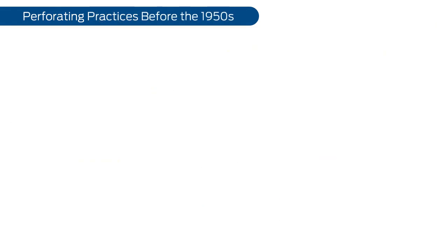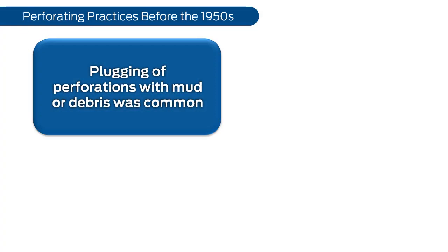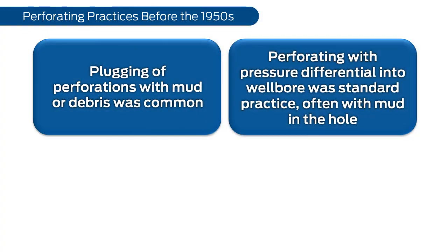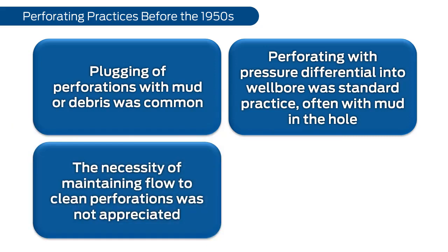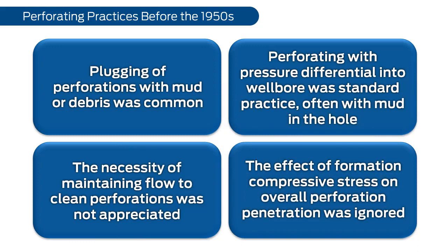Before the 1950s, plugging of perforations was common. Perforating practices and operations were carried out without a concern for wellbore fluid environments, often with differential pressure into the well and with mud in the hole, all of which led to creating perforation damage. The ability and the necessity of maintaining clean perforations was not understood or appreciated. The facts of formation compressive stress and how this stress affects overall perforation performance was not really known or was ignored.